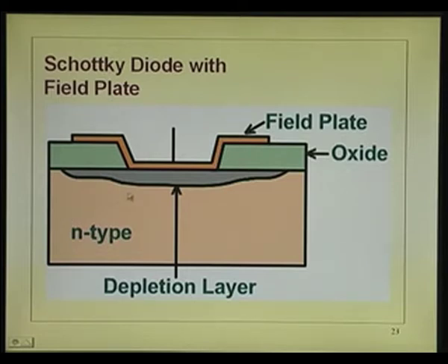Now, because it is going over the oxide, this portion where it would get crowding here, that voltage gets shared between the oxide and semiconductor. Now, you see here very carefully, the depletion layer which is wide here becomes narrower here like that, because of the voltage. I will just draw that here for clarity.